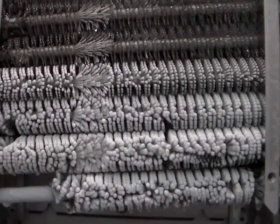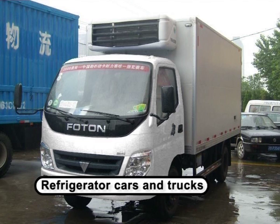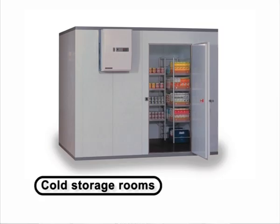Products near the refrigerator coils or at the bottom layers of refrigerator cars and trucks are most susceptible to freezing injury. To avoid freezing injury, the rail cars or trucks should be heated during transportation in sub-freezing weather, and adequate air circulation must be provided in cold storage rooms.